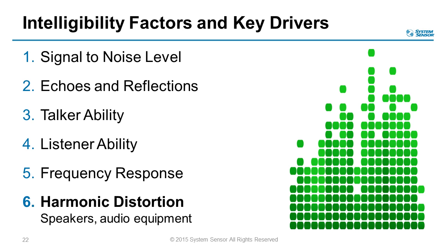The last factor is total harmonic distortion. This is another key factor that can affect intelligibility. Audio signals suffer from distortion as they pass through the electronic circuits. The distortion can be introduced by various components in the voice evacuation system, and the effect can be cumulative. Systems designed with low harmonic distortion tend to provide voice messages that are more intelligible. Distortion can be caused by damaged speakers, overloading your amplifier circuit versus the available power, the speaker installation, incorrect wire size, and message generators or recordings.